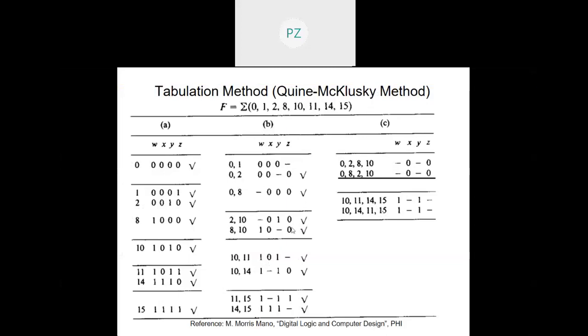In fact, you see, these two groups cannot be combined, so I should keep a blank here, so that when I need to go beyond this step, I know that there is nothing in it, so no further combination would be possible. This is a null group, so it cannot be combined with this, it cannot be combined with this, so I'll have to stop here. So that will give me the termination point. In fact, when no group can combine, that will be the termination point. So that is why it is important that I keep a blank group here. None of the terms here could combine with the terms here, so that is why a blank group. Now let us consider these two groups.